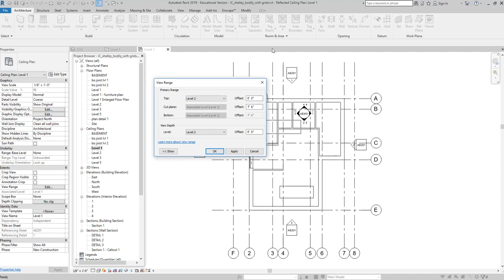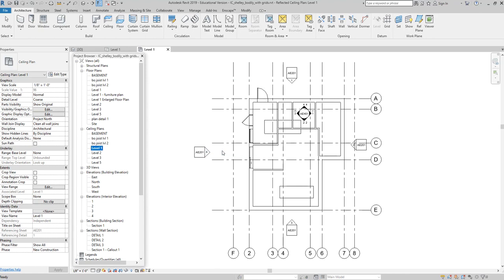looking up. Okay? So if we thought about that in terms of this room, if we look at that door right there, that door is probably like 6'8", 7 foot tall, right? If my cut plane was 7'6", it would be above that door and I'd be looking up at the ceiling, right? So if we were to look at a 7'6" ceiling cut plane in this room, I wouldn't see any of these doors, I wouldn't see any of these windows because my cut plane would be just above them all, right? And I'd be looking up and I would see all of the ceiling equipment. So the grid, and I would see the ceiling tiles and the lights and the projector and all that good